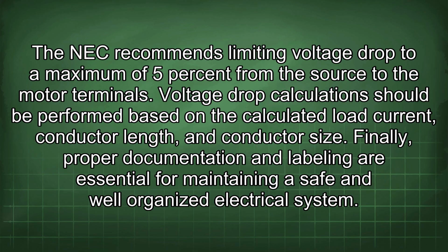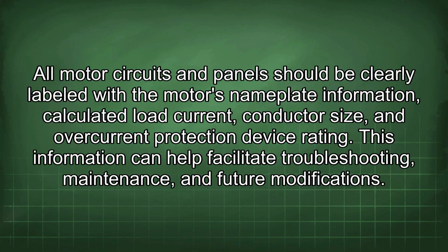Finally, proper documentation and labeling are essential for maintaining a safe and well-organized electrical system. All motor circuits and panels should be clearly labeled with the motor's nameplate information, calculated load current, conductor size, and overcurrent protection device rating. This information can help facilitate troubleshooting, maintenance, and future modifications.